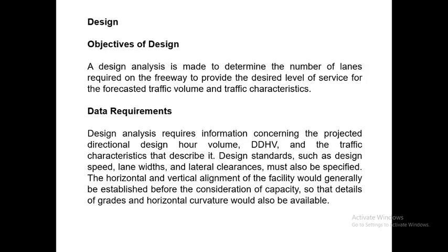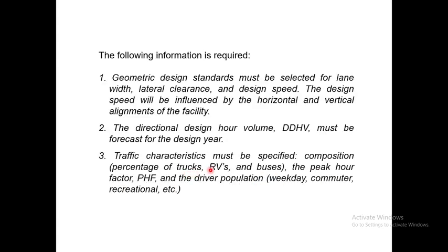Okay, so if you want to go through the other one, it is the design. As I mentioned, the design is for finding out what is the required number of lanes. So you usually have to calculate the number of lanes in the design, of course, but you may face different factors like DDHV, directional design hourly volume, and other traffic specifications.